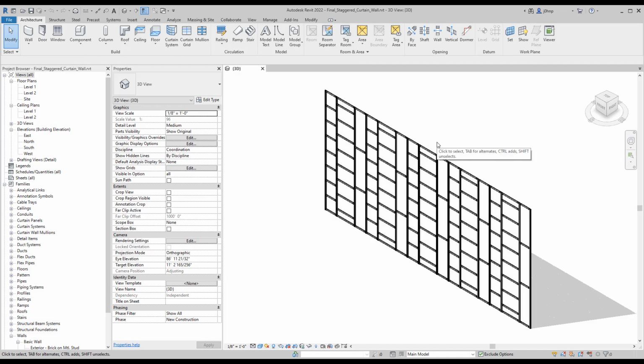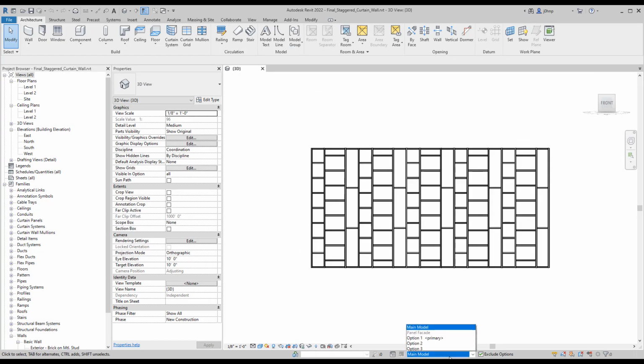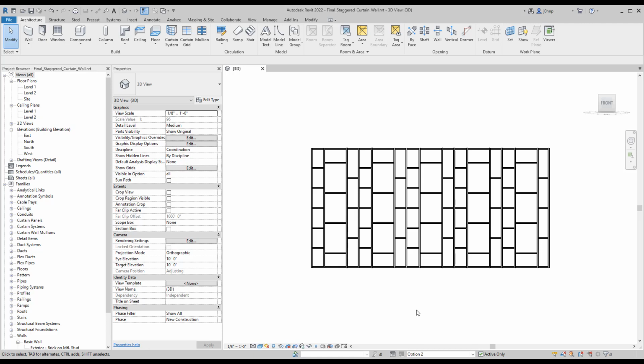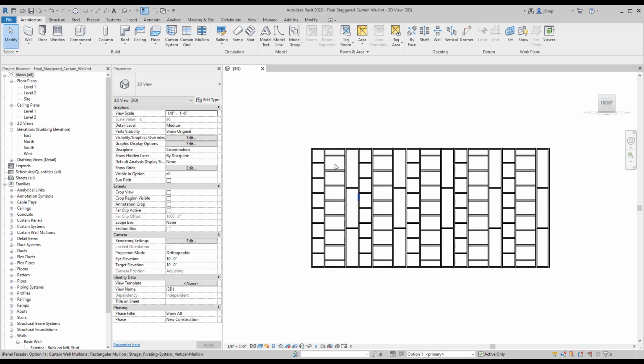All right, so if you were to run the Dynamo graph in Generative Design, you can get a result that looks something like this. So if we go to the front view, we can actually toggle through design options to see some of the results that we have from optimization workflows. So overall, the workflow does take this concept of modules and submodules to create a randomized curtain wall system for us to be able to evaluate. In the finished file, we do have 3 options pre-baked for you.